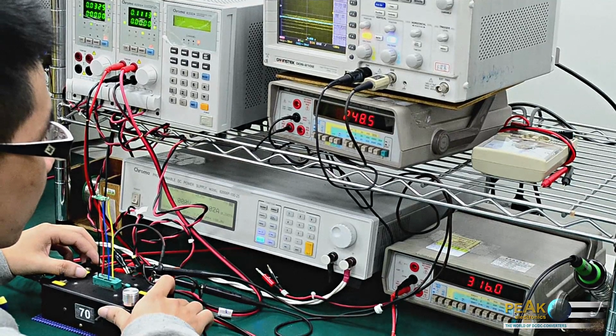However, in the interest of a long operating life, the DC-DC converter should not be taken to the upper temperature limit. In particular, capacitors suffer due to high temperatures. In practice, it is advisable to remain below approximately 80 degrees centigrade as measured in contact to the surface of the housing. With converters having an output power greater than approximately 20 watts, the efficiency should be as high as possible.